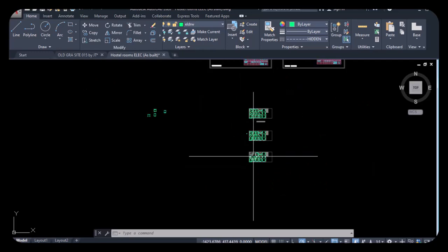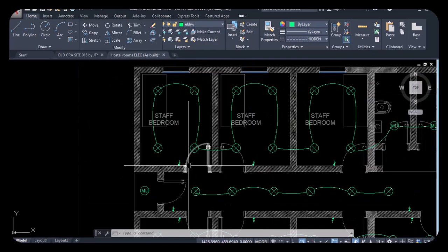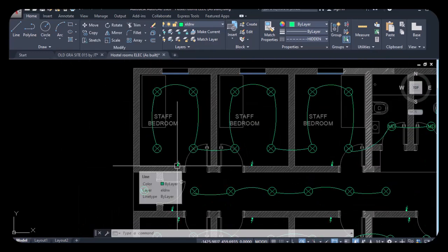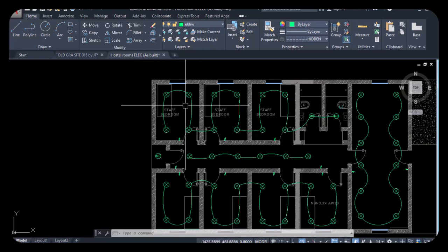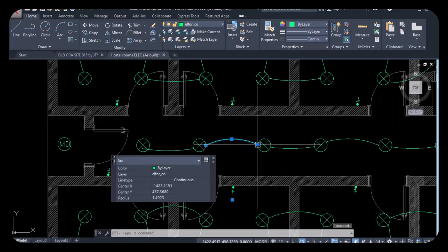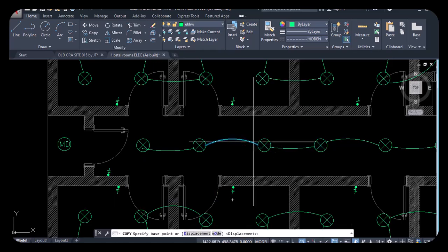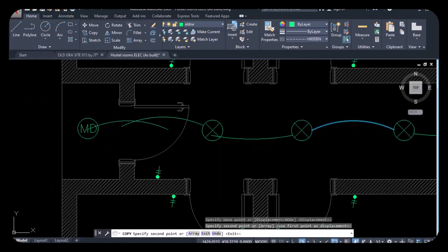Same thing we are doing here will also be done here. Remember, for the light, we just introduce the switch. And remember, we also introduce breakers for each of these lights. You can see that this light started from this point, moved to this point, and then it terminated here. So these lights will be grouped on one breaker. You can see this one, same thing, will be grouped on one breaker. This one also will be grouped on one breaker, and this one will be grouped on one breaker. So this, also copy this. For the new lighting, start the cabling.